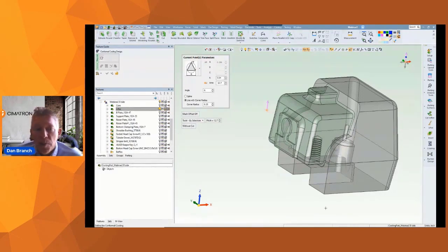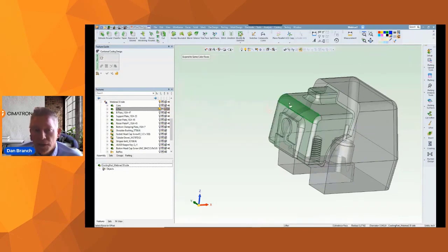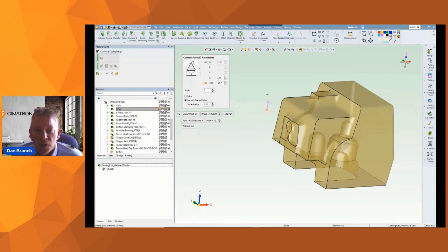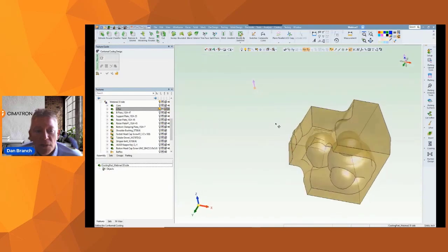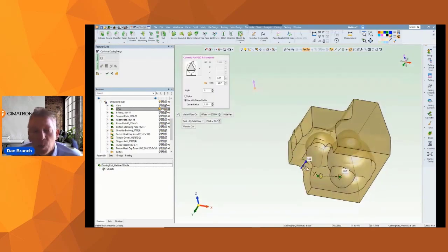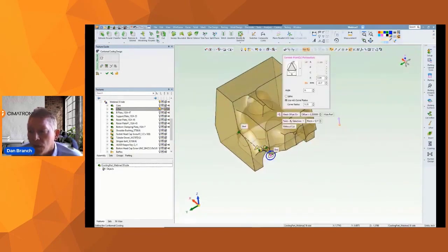Now, the system wants you to define the path, and you could spend a lot of time thinking about it, drawing a bunch of very specific curves through a part. But let me show you our cool idea to make that easier. I want the system to create a new lifter body, one that has every face offset inward from the actual steel. So theoretically, if I plot a course across this new body, the cooling channel is going to be at a constant depth from the skin of the lifter, the actual surface, to promote good heat transfer. So here I'm actually going to give it a little more realistic offset. We need some room. And then just start picking points that will lay out a conformal cooling pathway.